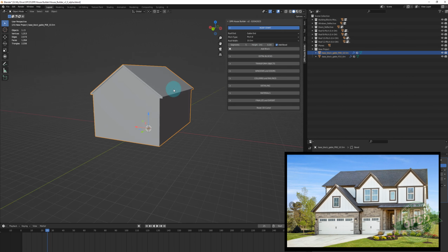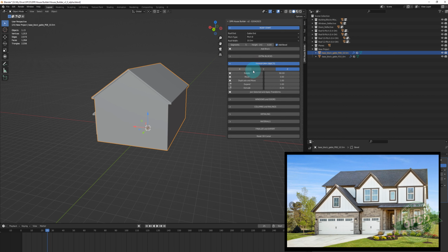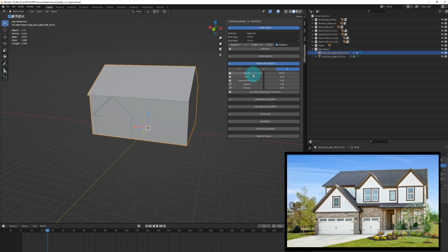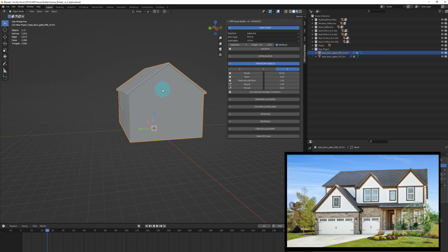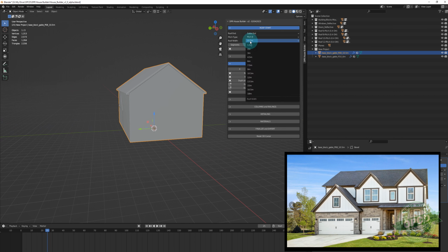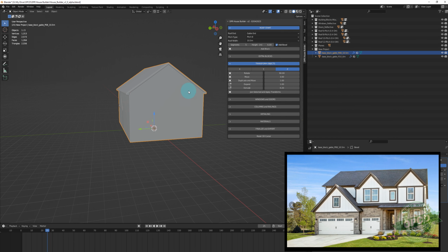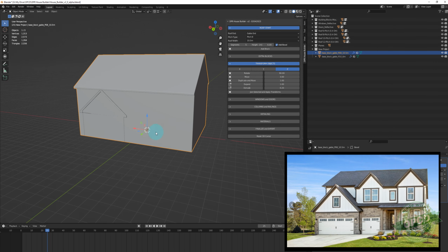Now it's turned sideways, so go to the transform objects. The Z is your vertical, so we're going to want to rotate around that Z, and that's 90 degrees. So just click the word rotate, and that puts us where we want to be. Now if you don't like that, obviously you can go wider or shorter. That's just this block here along the top is running from here to here, left to right, 10.5 meters. And we're just going to go with that for now.